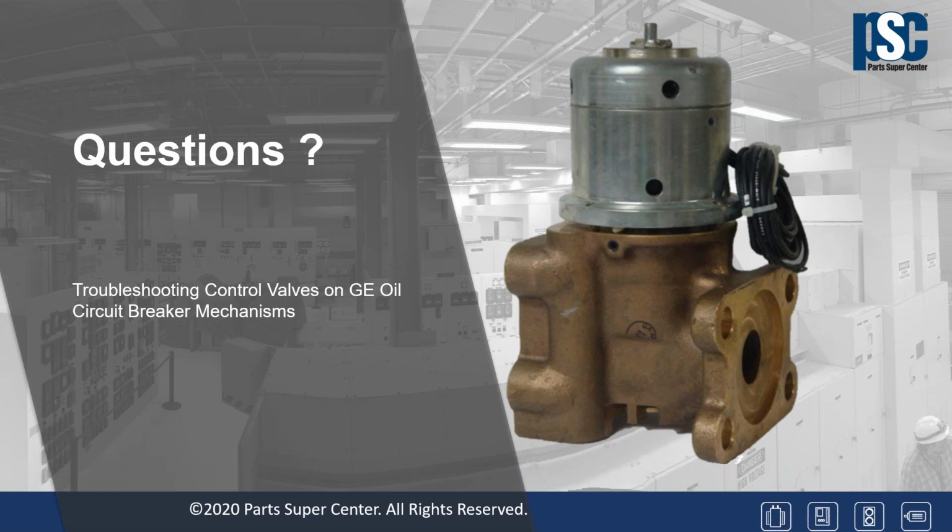We will provide a new pilot armature seat, a new pilot armature, all new seals and gaskets, as well as a new pilot armature bias spring, and the bias spring that sits directly above the main piston in the lower valve body. So when you get that valve back, it'll also have a new coil, and it should be better than new. It'll go through all the same production tests that a brand new valve would go through.